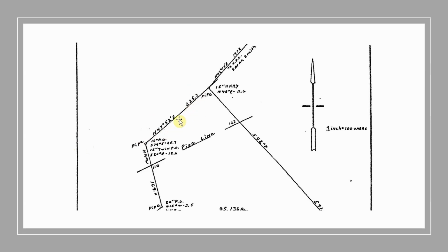Reference that legal description, which was at least done by typewriter, and make sure they're matching, they're in sync. And if this doesn't match that legal description, and maybe you can't recover one of these pipes in the field, that legal description is going to hold the most weight if you can't properly recover or validate the location of that pipe.